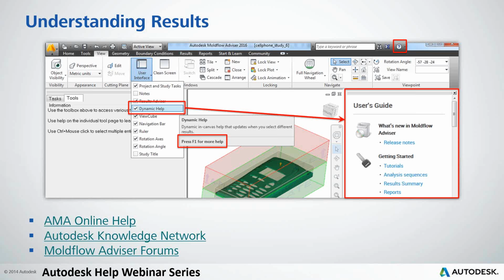Alternately, you can go to the top right corner of the Moldflow interface to that little question mark, and that'll bring up the help pages for Moldflow Insight. And you can navigate through those at your own speed and pace and do any searches through there as well. That keyword box there is also nice to help doing an impromptu search, and all you do, go in there, type what you're looking for, say fill time result, and it'll pop up with the help files for that.